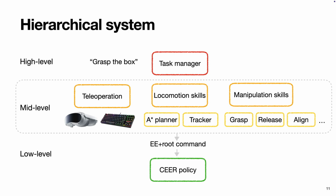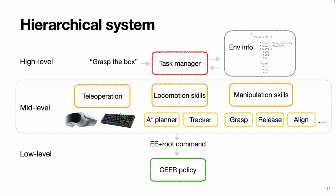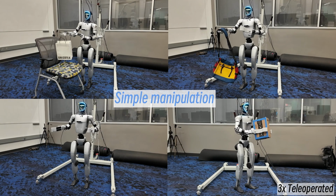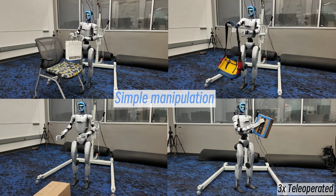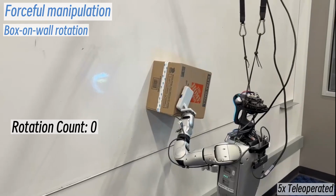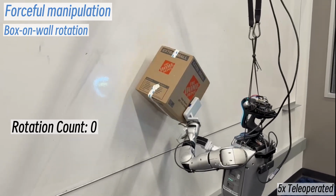For example, if the user gives the natural language command, "grasp the box," the task manager first queries the environment, reasons about the task, selects the grasp skill, generates the corresponding End-Effector and root command, and sends it to Seer. The robot then executes the grasp through the low-level policy. Now that we have introduced the full architecture, let's look at how it performs in practice. We first show teleoperated contact-rich tasks to evaluate Seer itself, and then long horizon room scene tasks to evaluate the full hierarchical system.